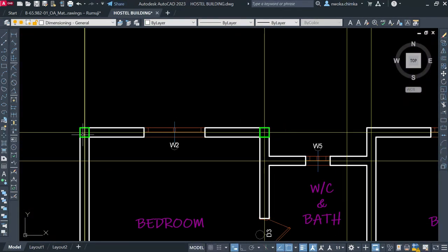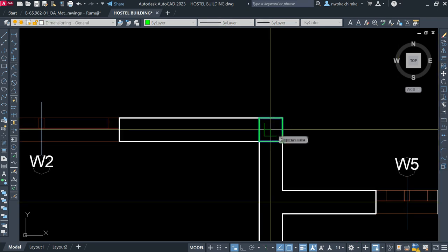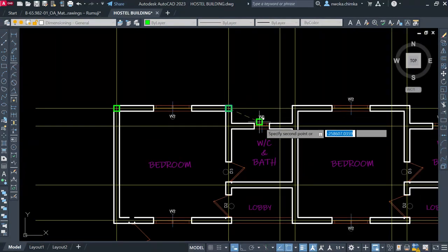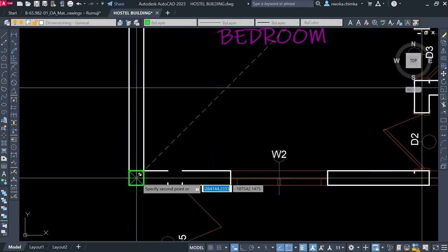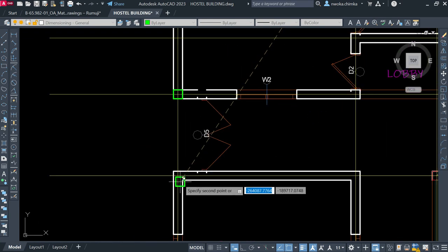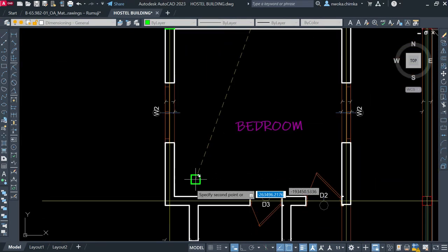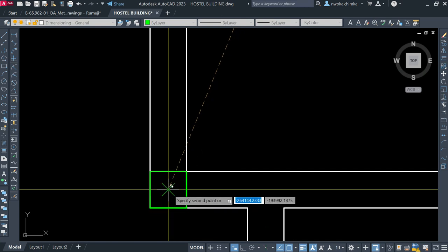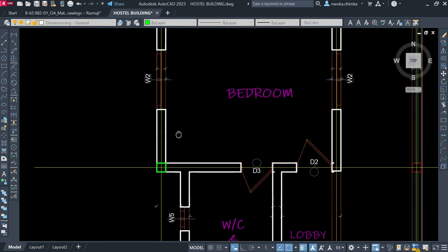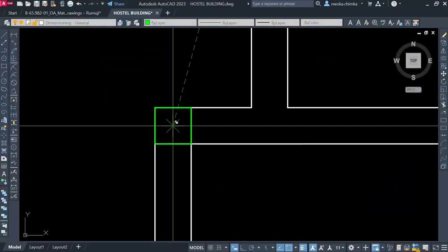Now, column distance between columns: since you are a beginner in structural design, I would say you should be guided. Let your column distance be at most 6 meters. The reason I'm saying that is that you will not have issues in your modeling, until you are strong enough to go ahead to 11 meters, 10 meters long spacing in concrete building. But for now that you are starting up, I would say you should limit yourself to a maximum column distance of 6 meters. So right now, you see I'm placing my columns just now.